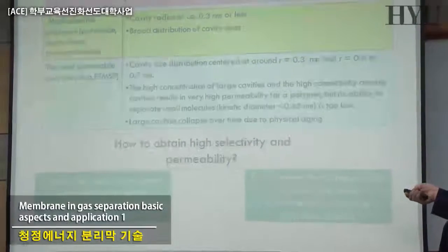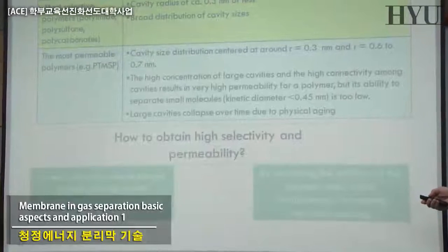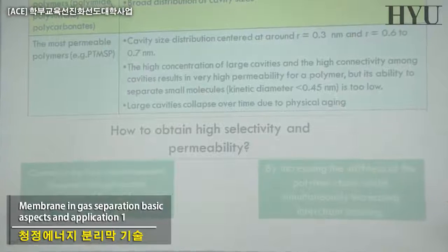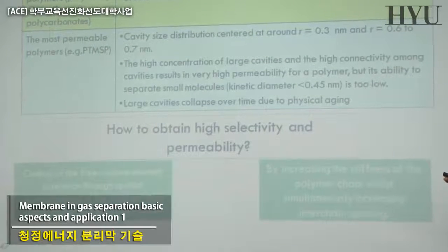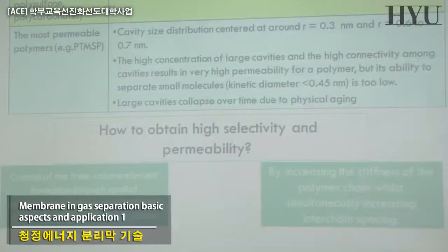And also the other problem which exists sometimes with this kind of material, the polytrimethylsilylpropene, I told you, is not stable with time. So the large cavities, which are quite interesting at the origin of this selectivity, collapse. They are destroyed, and this problem is irreversible. You cannot restore the properties. That's why this very interesting material never succeeded, until now at least, to become commercial.